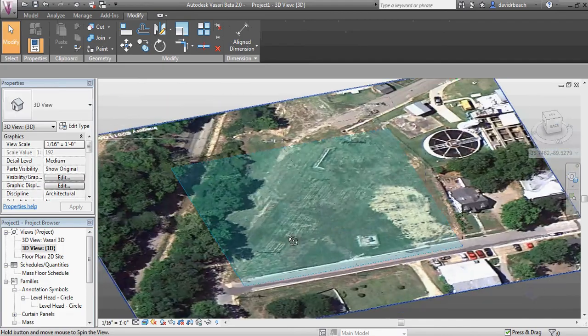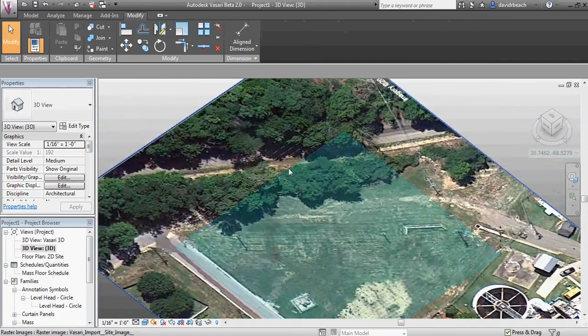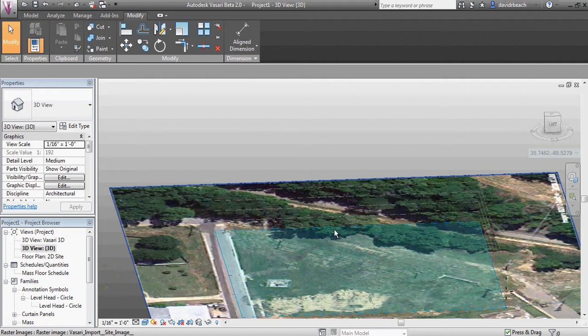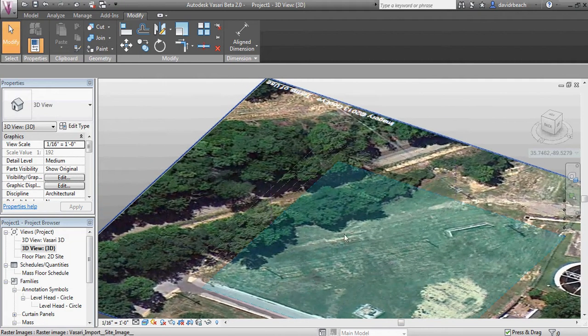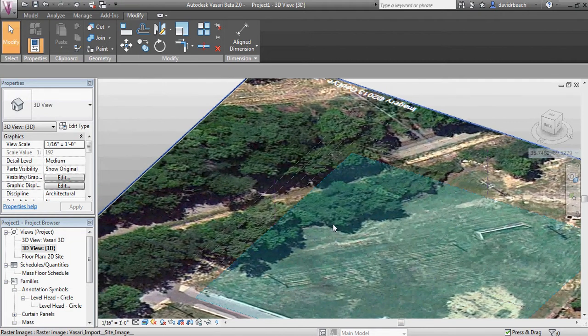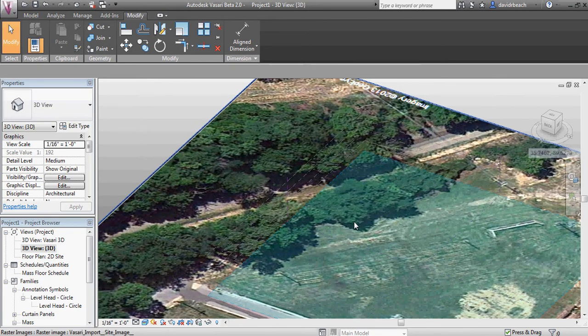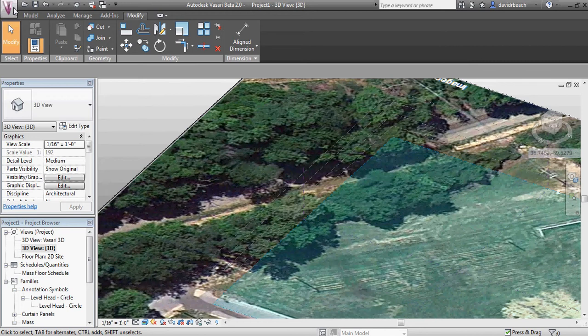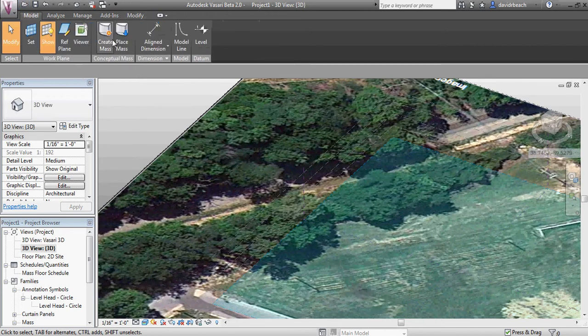And let's actually look at making a more precise massing model object. So I'm going to start again on this lower level reference plane, level 1 reference plane. Even if you're working with a 2-story building, and a lot of you had a building that was going down into the ground, we're not going to worry about that right now. We want to keep this simple. You're learning the software.